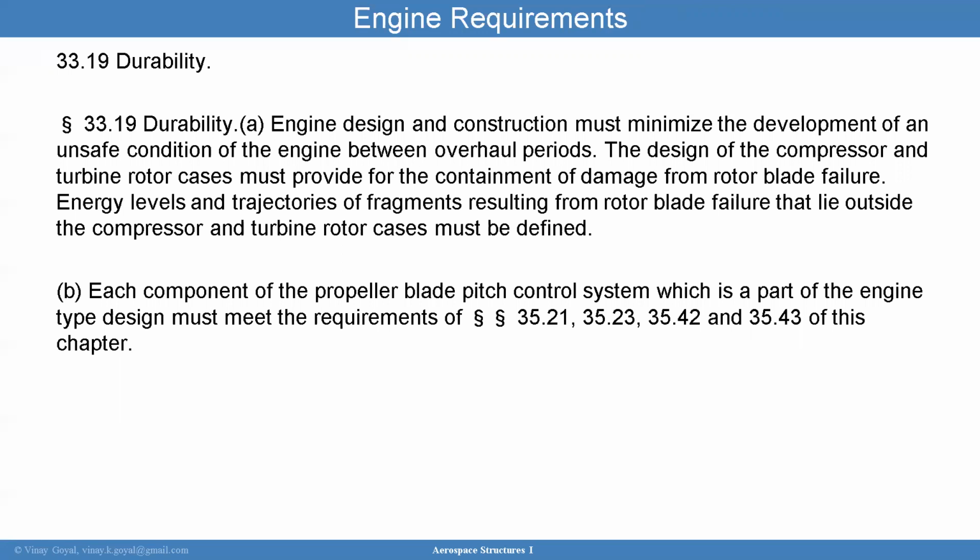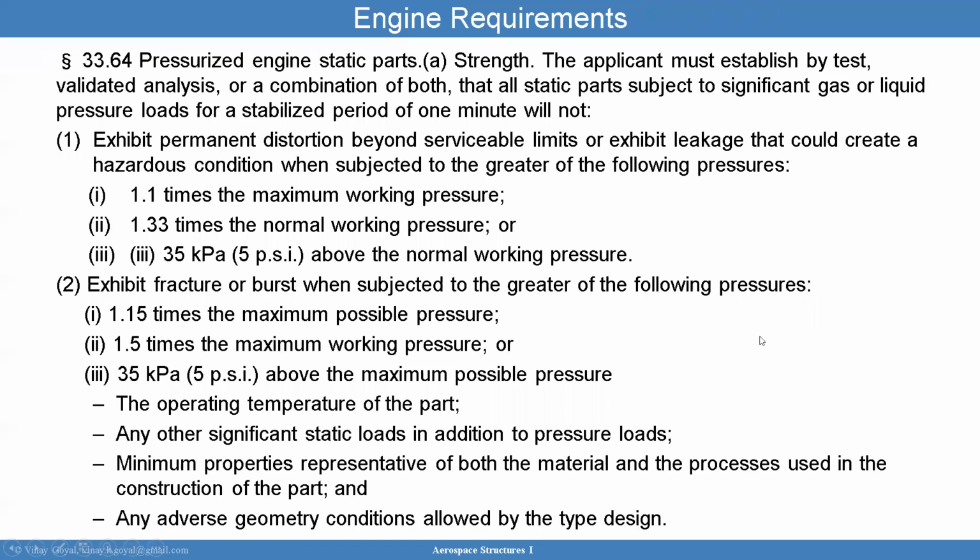Energy levels and trajectories of fragments resulting from rotor blade failure that lie outside the compressor and turbine rotor cases must be defined. Each component of the propeller blade pitch control system, which is part of the engine type, must be designed according to this section. So I'll let you pause the video and download this so you can read more.